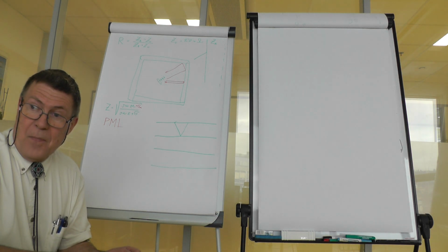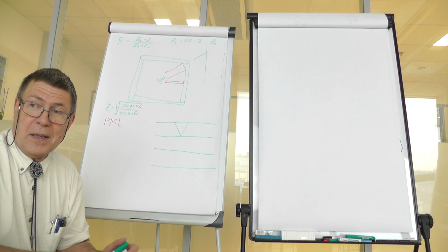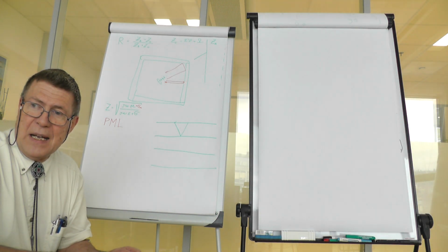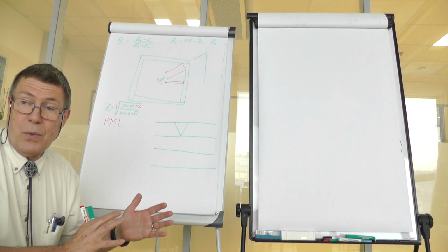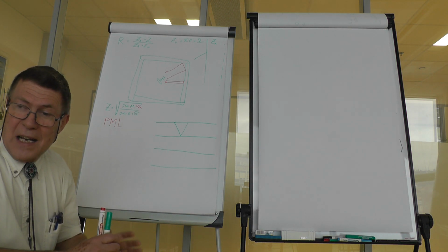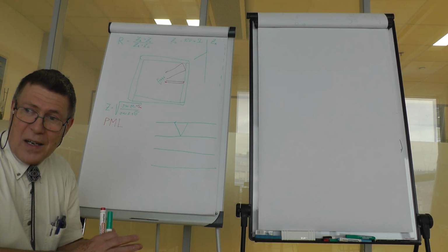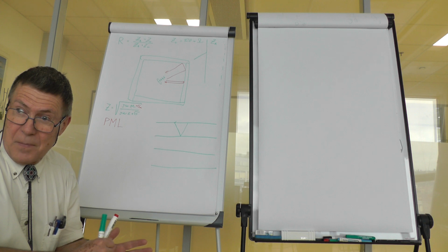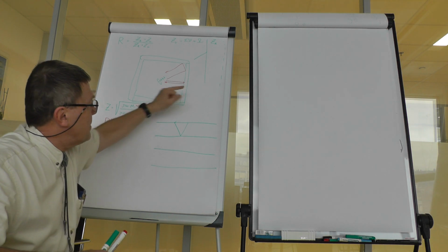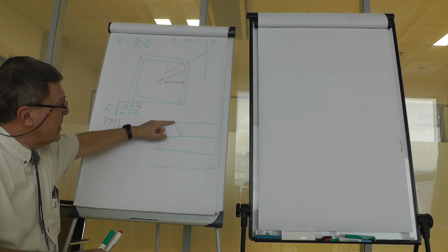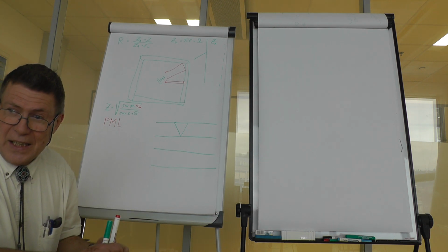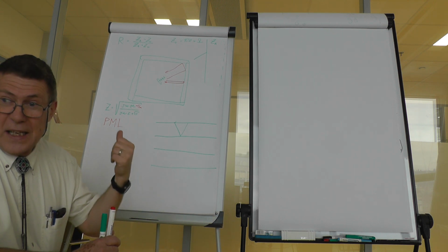but as a numerical model can provide a non-reflective termination of a grid. And this is mostly achieved by a set of equations that mimic anisotropic or even bianisotropic materials in which both permittivity, conductivity, and other properties of the material are orientation dependent, which tries to keep the energy inside the material so that the energy does not propagate through but propagates along the layer and does not get out.